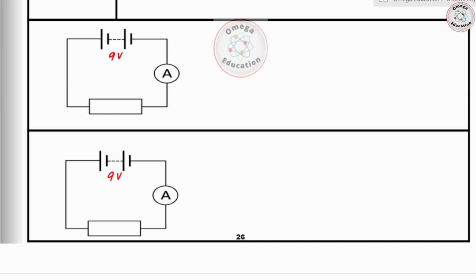All right, and then in the first circuit we used an ammeter. This one, an ammeter, like I said, is a tool that is used to measure the amount of current in the circuit. All right, the convention is you should be connecting it with the positive terminal of the battery. That's the convention. But anyway, since an ammeter does not give you the direction of the current unless you have a digital one. On the digital one you can get a negative sign.